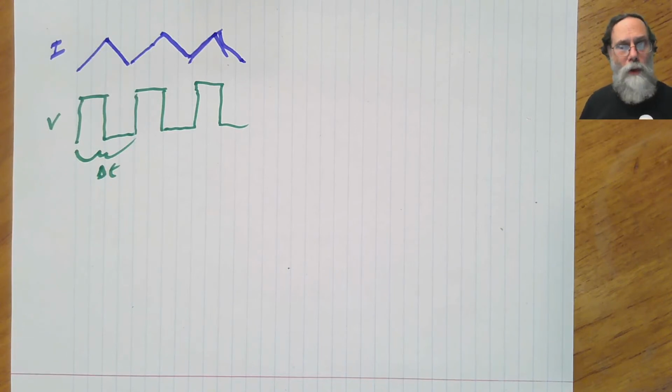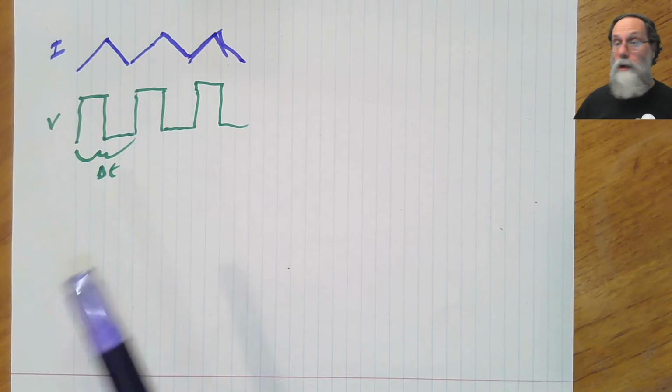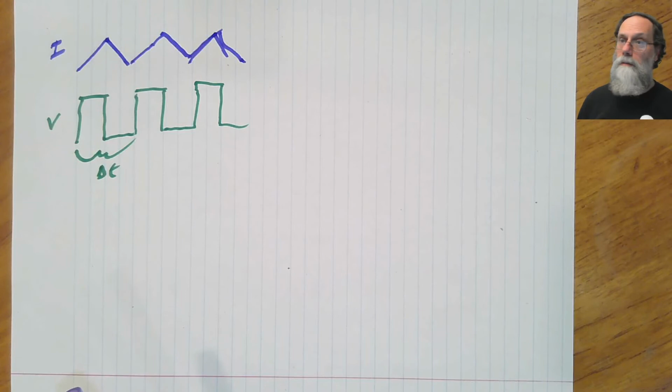And for a lot of things like motors and loudspeakers, the current is really what we care about in terms of what's driving the magnetic field that's causing the motion. So a lot of times you can put PWM signal directly into your motor or your loudspeaker, and that's it. You're done. The small changes in current give you very little. Basically, the inductor itself is doing the PWM to analog conversion for you. That's not the only way to do it, though.